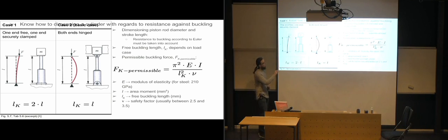And these kinds of setups, you can find a lot of in the Blue Book, the Mechanical and Metal Trades Handbook. Often it's just for regular steel rods that are clamped or hinged or have different solutions done to them, and they're going to tell you what the buckling length is going to be. But you can transfer it easily to a hydraulic cylinder by just thinking like this instead. We'll do a 15-minute break before we continue on with the cylinders.